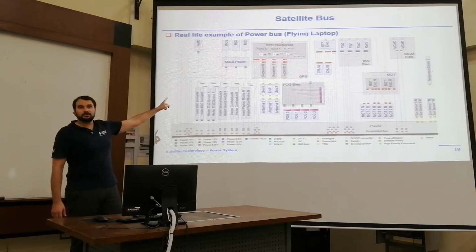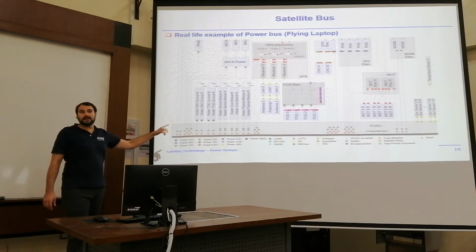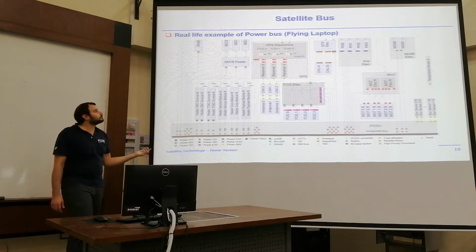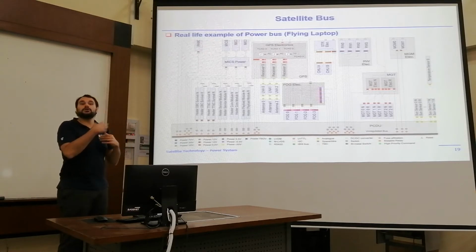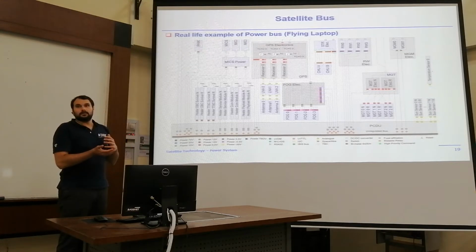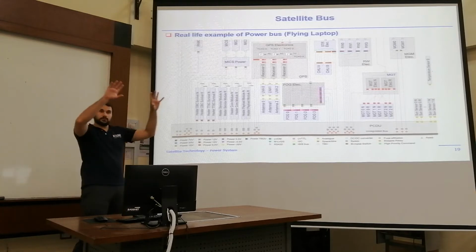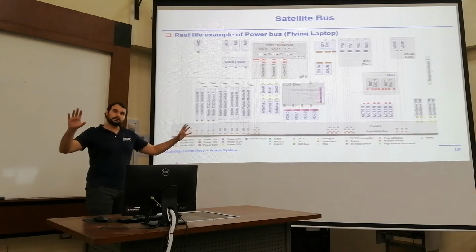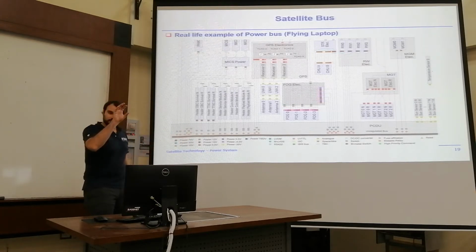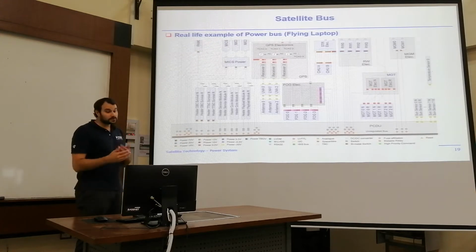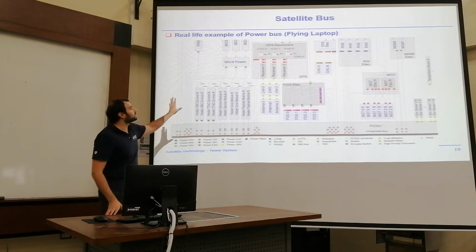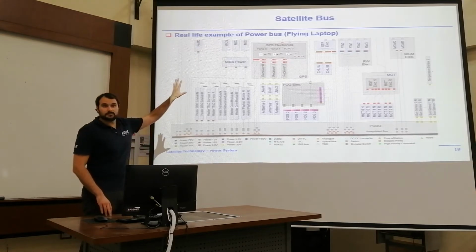Those other components are fed with unregulated power of up to 70 volts, and have their own power box that regulates the power for the unit. So you can distribute your power unregulated and then have several units take care of the power conditioning. Those are the two concepts I just want to show you with this plot here.